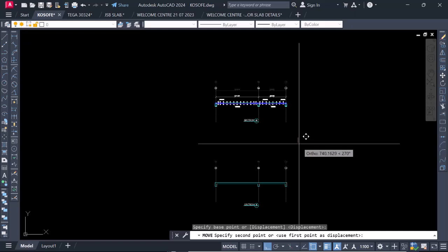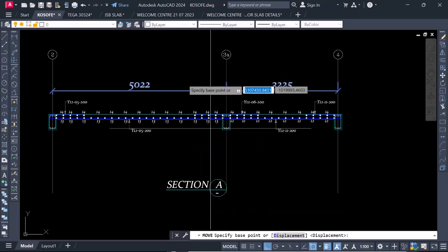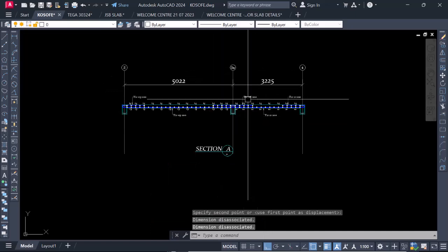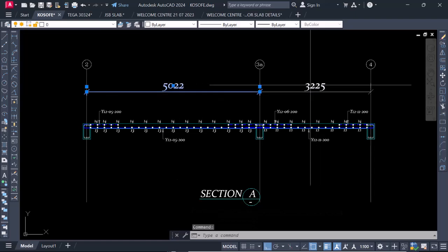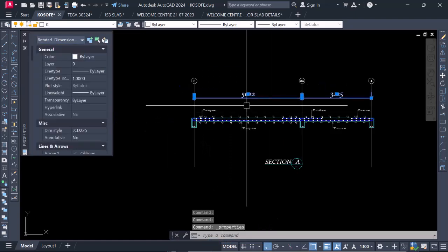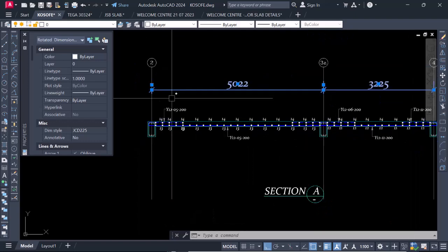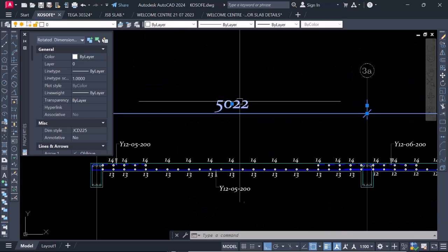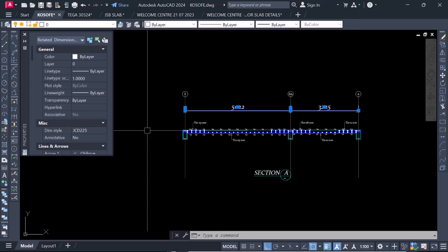There's something about this area, all right? Push this up, okay? So you can see that this text is very big. So what we're going to do, we're going to match the scale. We're going to scale this text and make sure that they are falling in line with what we have, okay? You want to make sure that your text, one is not bigger than the other. You can see what we have here is the same thing as what we have here. You can see the same property with this, all right? Even though they have different fonts, you can see that they are all together. So your text should not be so big, apart from your call out text, all right? Your call out text should be a little bit bigger.